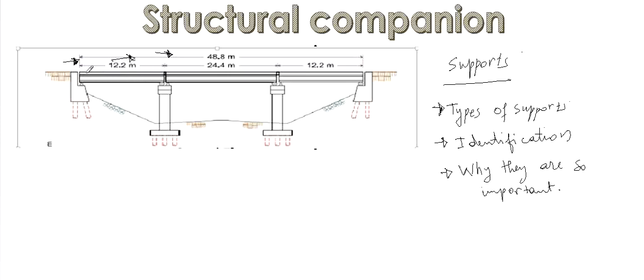This is the bridge deck here, and this is another deck of the bridge, and this is another one. So the loads are transferred to the bridge deck, and then from the deck to this component here and this component here. These are the supports of the bridge, because the load is transferred to this structure, and then from this one to the footing, and the footing transfers it to the soil.